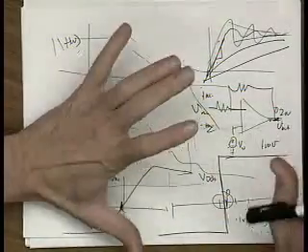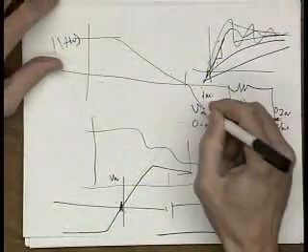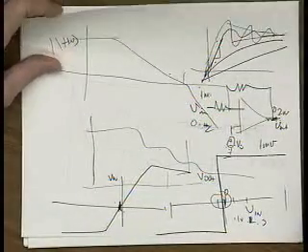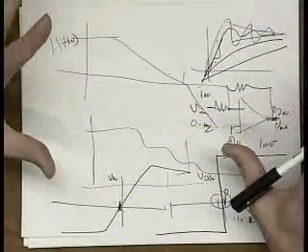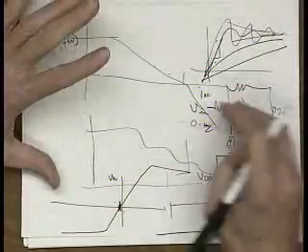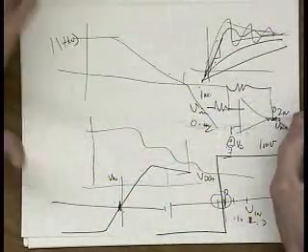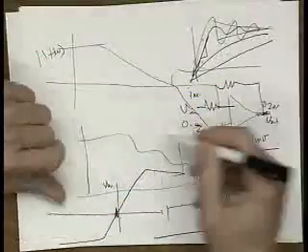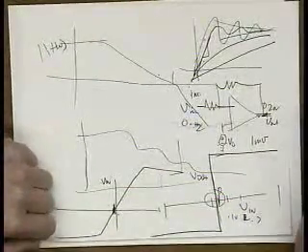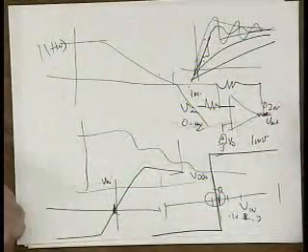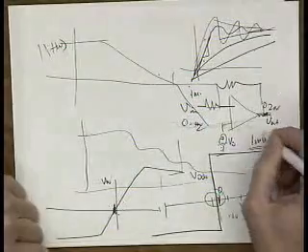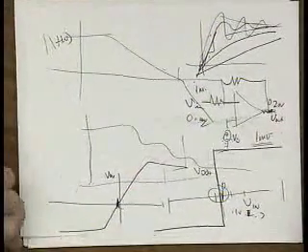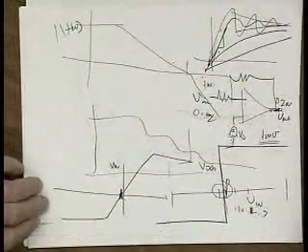Okay. Changing the offset here is the same as changing the voltage there, of course. So use offset voltage in the early stages when you're trying to get your gain, so you make sure that you DC bias so the output's at 0 volts, and you can work on your open loop response. And then in the end, you have to make sure, of course, that it's less than a millivolt, because that's one of the specifications. But that's for all processes.